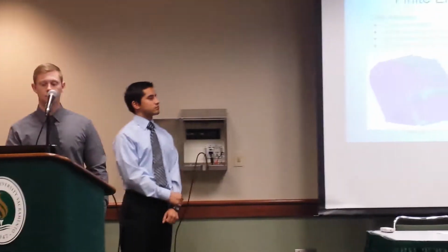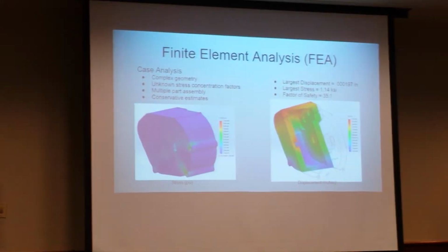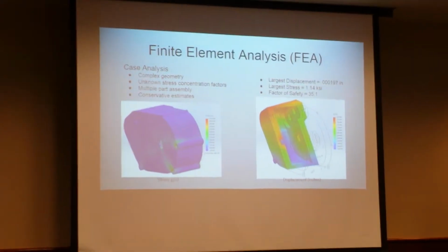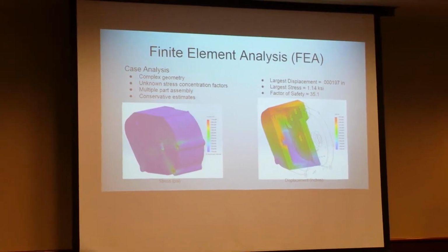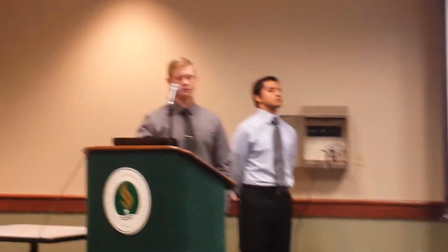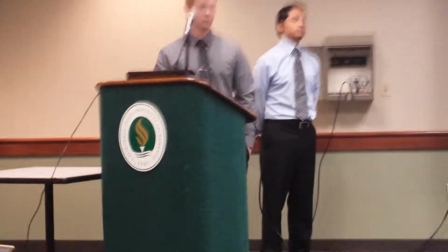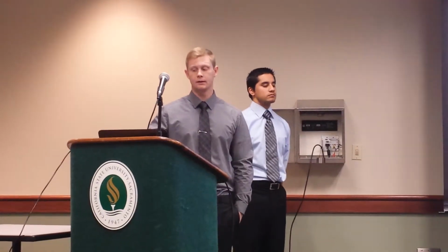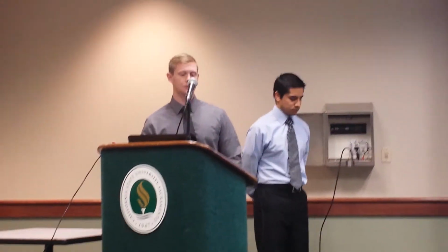For that, we get the largest displacement of about 1.9 10,000ths of an inch, and the largest stress is about 1.14 KSI. That leaves us with a safety factor of 35.1, so this is quite a robust design, and will be able to handle any additional impact loads this may receive, especially during an open wheel race.